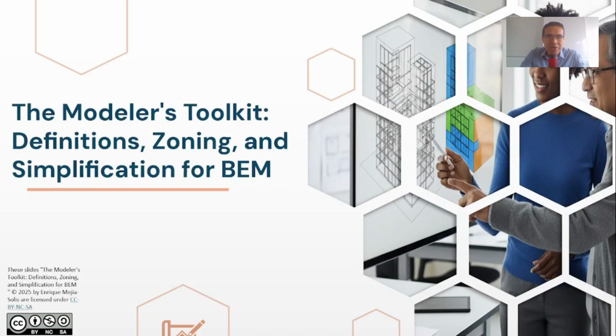In this introductory module, we are laying the foundation for effective building energy modeling. We'll start by clarifying the core terminology, the difference between modeling and simulation, and defining the key concept of a thermal zone. We will then dive into the strategy of BEM, covering two crucial practical skills: how to effectively zone your building model and the rules for simplification. These are the decisions that determine whether your model is accurate, efficient, and defensible.